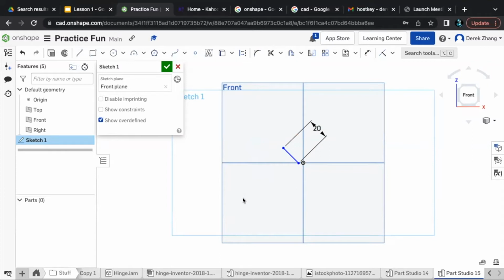Make sure the line, okay, so in OnShape, when you're hovering over something, like you can hover over these lines, they all turn yellow. And that's how you know when you actually hovered over it. And then you click once and then click backspace and it should delete it.